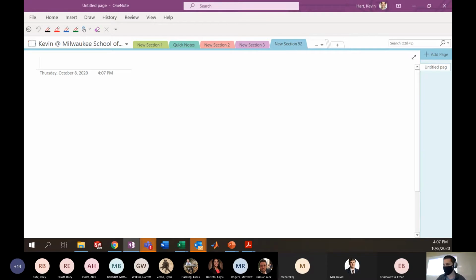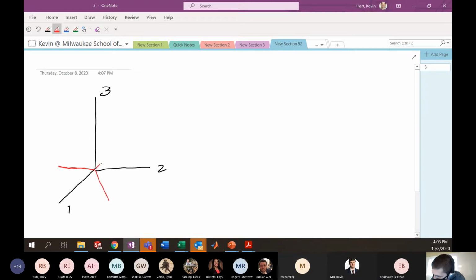If you have one general coordinate system, the 1, 2, 3 coordinate system, and another coordinate system aligned differently, X, Y, Z, let's say, then you can transform your stresses, strains, stiffness matrix, compliance matrix, etc., to that alternate coordinate system or back using a variety of different transformations.